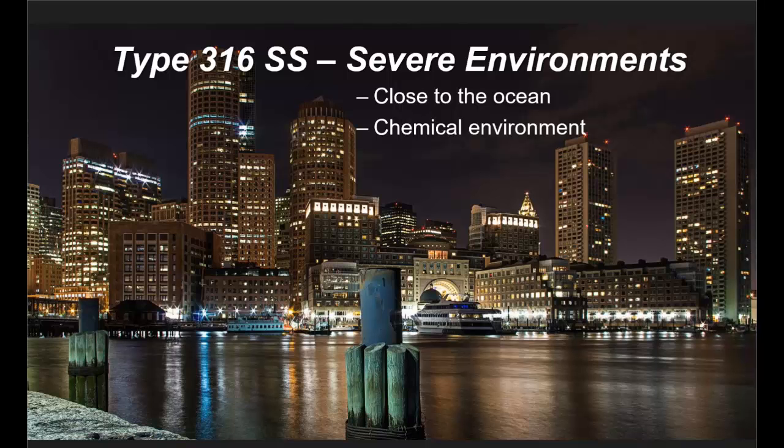It is available in 316. I don't even know if I mentioned it, but typically everyone goes with type 304 stainless steel. Just know that type 316 is available in all of the products that are stainless and all of your accessories that are stainless steel. This is what you would want to use if you have a really chemical, harsh environment, you're close to the ocean. It just stands up a little bit better in those corrosive areas.